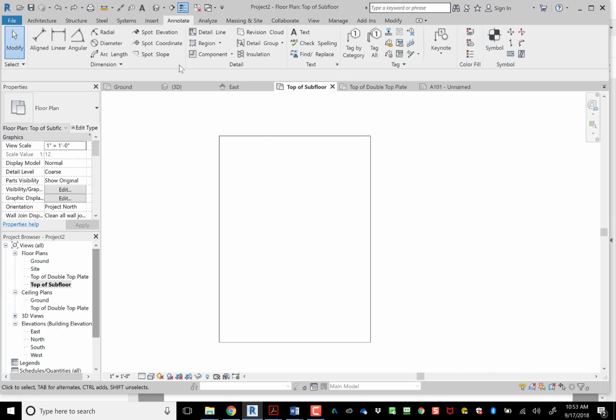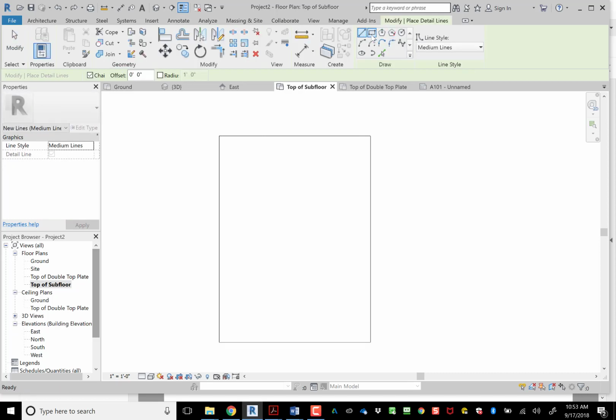Actually, the sheathing should have gone on the outside of the framing. Sorry, let me do that again. To do that, I do a rectangle, I do the offset of 1/2 inch, or whatever the sheathing is, and then I choose my corners. Earlier I flipped it to the inside, but now that I think about it, the sole plate sits on top of the edge of the subfloor. The plywood then hangs down lower, so it's going to go on the outside.